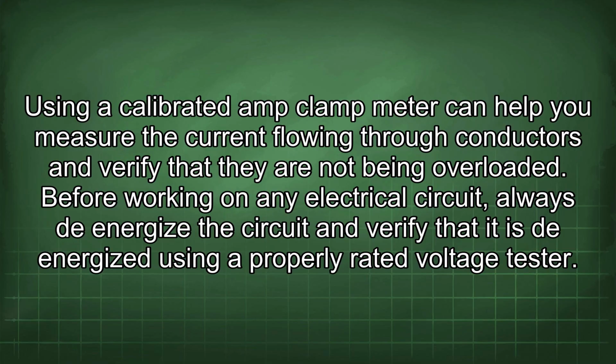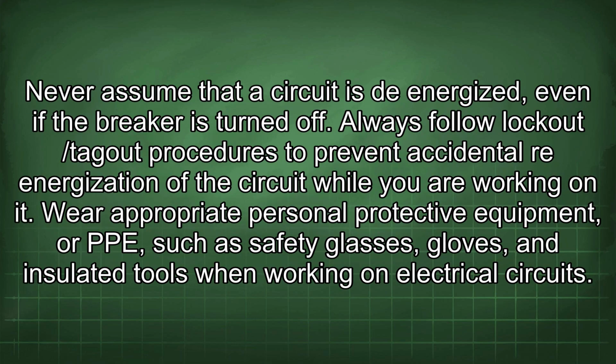not being overloaded. Before working on any electrical circuit, always de-energize the circuit and verify that it is de-energized using a properly rated voltage tester. Never assume that the circuit is de-energized, even if the breaker is turned off. Always follow lockout/tagout procedures to prevent accidental re-energization of the circuit while you are working on it.